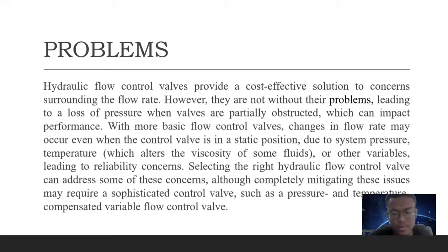Problems. Flow control valves are used to regulate the flow of fluids. Control of flow in a hydraulic system is critical because the rate of movement of fluid-powered machines or actuators depends on the rate of the flow of the pressurized fluid. It is important to understand the parts of a flow control valve and the types of flow control valve that are suited for a specific process, so that the actual results of the process match the expected results of the process.